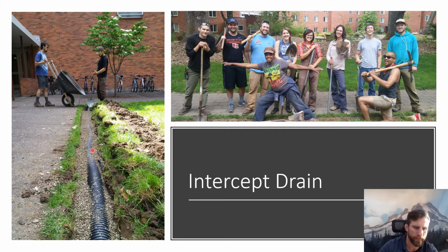Okay, there's a final picture on the left over here of our intercept drain. You can see we trenched it in relatively shallow. We put fine gravel over top of it. We're going to then put a layer of sand over top of that to finish up the drain tile system and hopefully provide something that can allow for relatively rapid drainage of water that rolls across the driveway or the sidewalk here, or across the native soil here to the drain line.